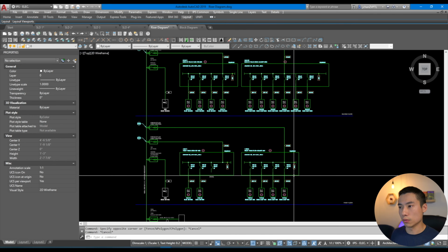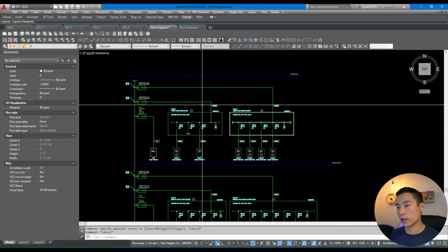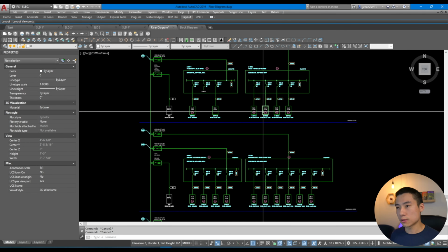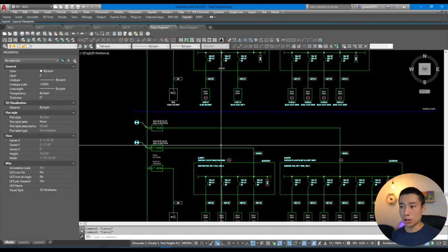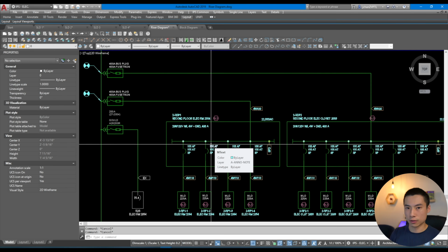But if you were to keep going up, you'll see that each floor has more and more information with the floor indicated. So a riser diagram can be simpler than that. You don't have to draw out the distribution board. If you really wanted to, you could, I guess, blank this out and then have your single line separate.